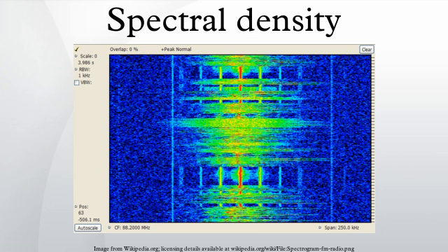In the case of the voltage of an electric signal, the squared signal is proportional, except that it has the wrong units, to the power of the signal, and so even in statistical applications which use different units, the spectral distribution function and density function are often referred to as the power spectral distribution function and the power spectral density function, although the word power is often omitted for brevity in contexts where no misunderstanding will arise.